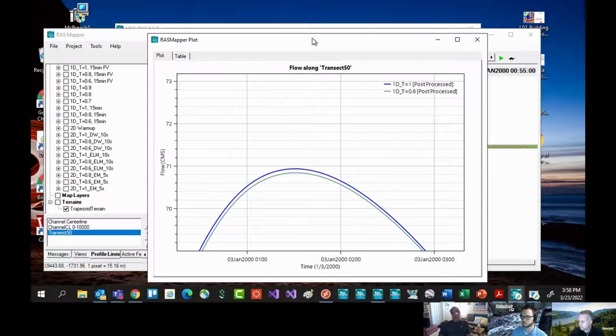Yeah, the other thing about this is I'm betting that you picked a really good cross-section spacing already and have a really small time step. So you've already taken out of the equation diffusion due to, excuse me, is that a word? Let's not get too technical, Gary. Yeah, just in case some people aren't following. So you've kind of taken out of the equation already any kind of attenuation or numerical diffusion due to the space distance being too long for the wave being modeled and the time step. And when you do that, differences because of theta become smaller too.